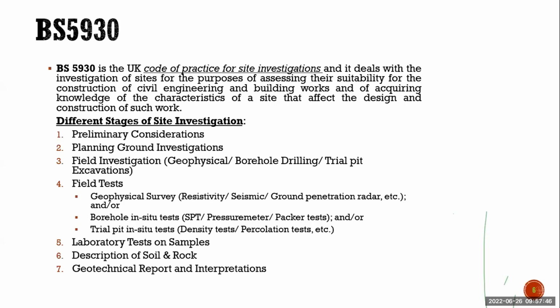And if I use the 100 kg hammer instead of the 63.5 kg hammer, then where the penetration with the standard hammer takes 10 blows, with the 100 kg hammer the number of blows will be maybe only 8 or 7. Now the N value varies for the same kind of strata. So in order to speak the same language, we have to follow a specific standard.